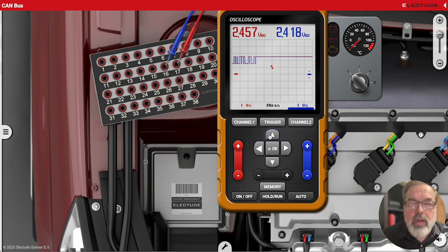And if we look here, we've only got 1 signal here. We're getting a ghost image because there's still a connection between the two through this parallel connection. We're getting a ghosting of one of the 2 signals on the other. So which one? Let's just pause this for a moment and let's start doing some counting here.